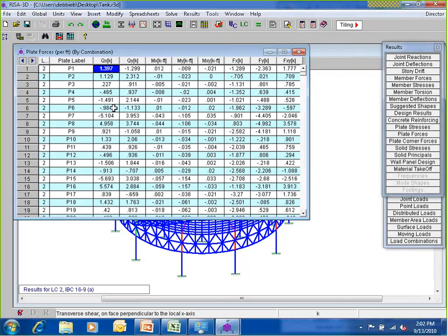For steel, if we're looking for stress points, we may want to make sure it's submeshed real tight. For concrete, where we're more of a blended average, we might not worry about what's happening on one tight plate, so submeshing might not be as crucial that we make it real small and fine. What we've got here is also, we can look at the bottom of the screen.